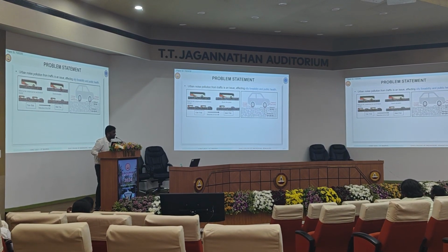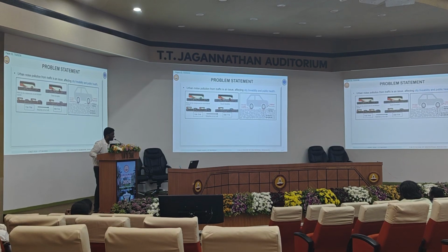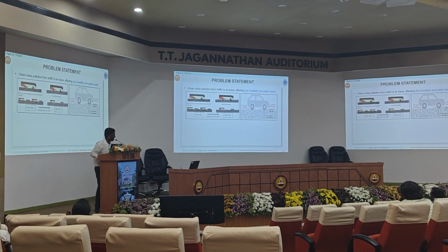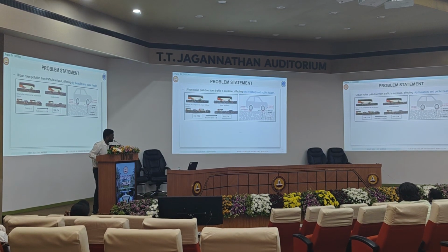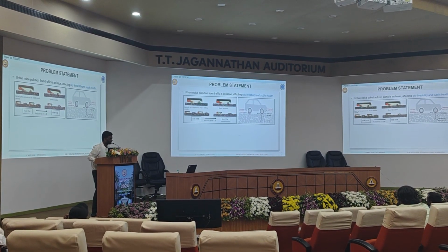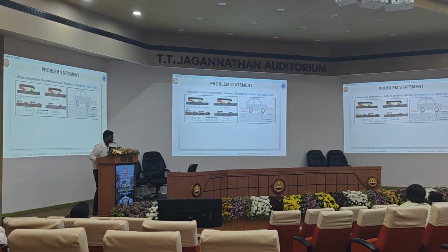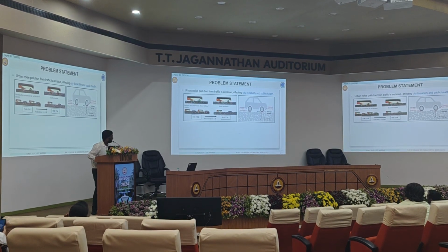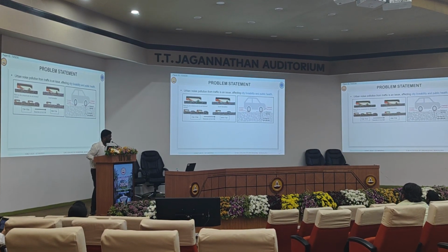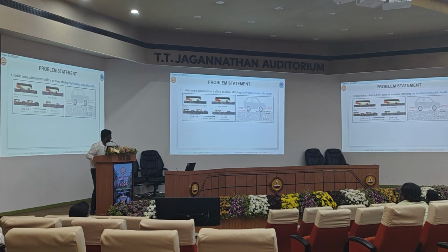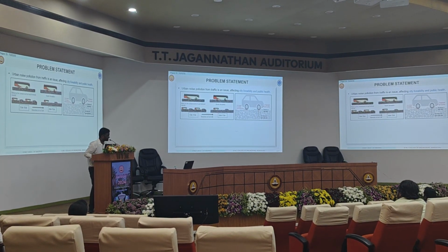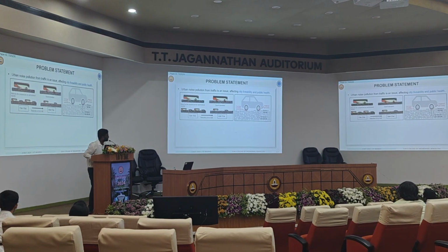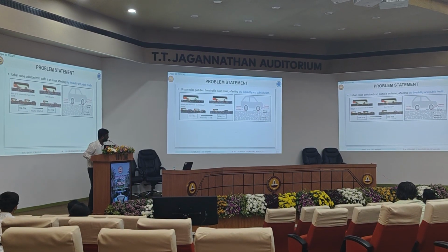Dense graded pavement generally makes more noise in comparison with open graded pavements, as per the research shown, where there is a significant amount of noise absorption and transmission through the open graded pavements. From dense graded pavement generating noise anywhere in the range of 73 to 78 decibels to 68 to 73 decibels, there is a significant amount of noise reduction. Through the air voids, the noise gets transferred and dissipated.